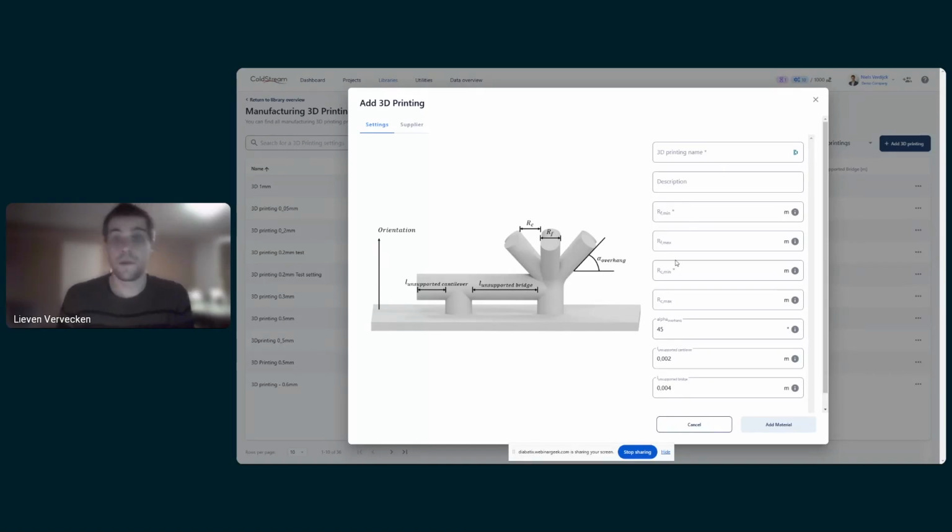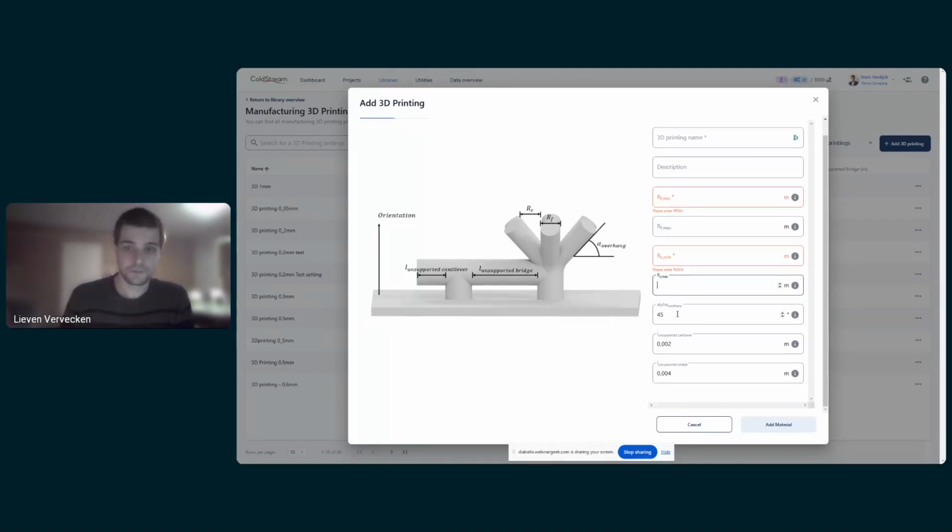With 3D printing, what you have control over is RF min and RC min, where RF min is the minimal printing resolution that your machine can handle. Same with RC min, the minimal channel width size, so just make sure that you have enough room for depowdering. You also have the equivalent maximum constraints, should that be of interest to you.